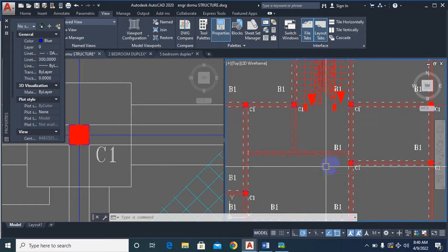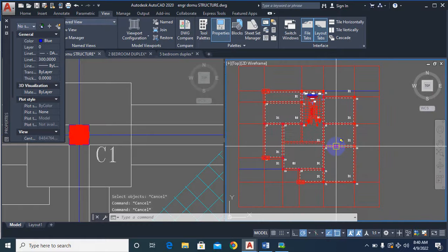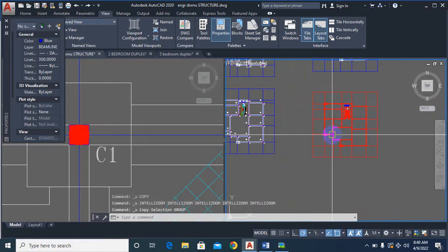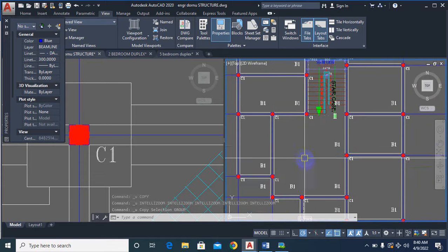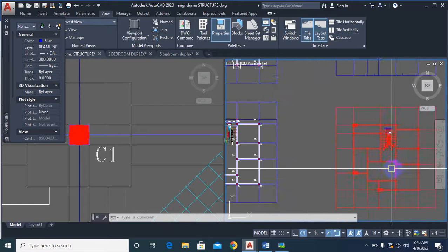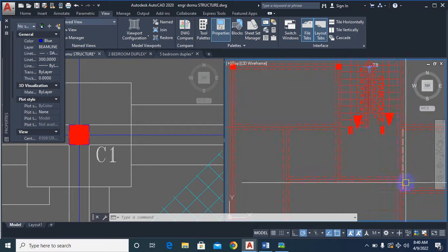But in a case where I place a column, let me go back, I'll take this back. Now you can see the whole of this is void. At the first floor level we have a drop beam here. So this beam is going to be acting as a point load on this.